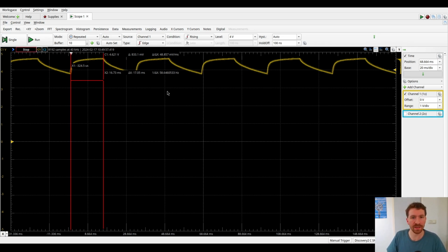The other thing that you might notice is that this is not a nice clean square wave. It looks like a capacitive kind of effect here. It takes time for it to actually get up to the level. And I think there are a couple of things going on there. I think there might actually be a capacitive effect from the board itself next to the LED.